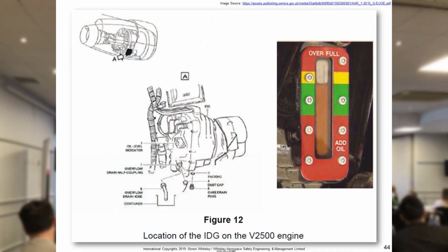So on that particular occasion, before the aircraft took off, there was some night maintenance performed by a team of 2 maintenance technicians. They were tasked to maintain various aeroplanes, and this was the second one that they were to maintain. As part of the maintenance for this aircraft, they were required to open the doors and look almost underneath to check the oil level for the electrical drive generator on the engine. They opened the doors, found that they needed some oil, but because they didn't have the tools with them to top the oil up, they decided to leave the doors as they were. They didn't latch them, and then they went off to go and get the tools that they needed.